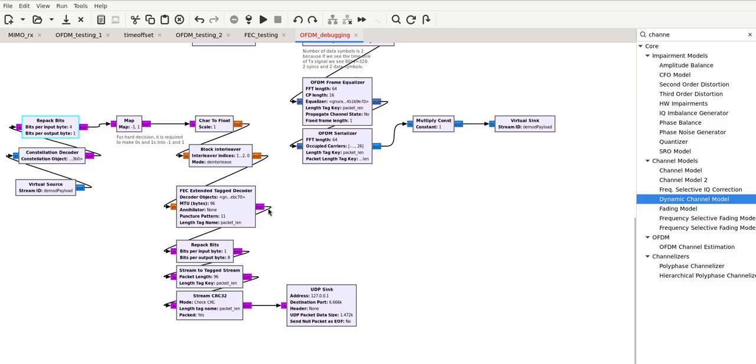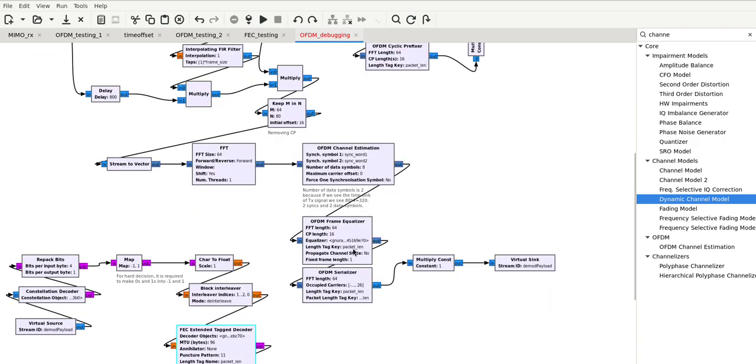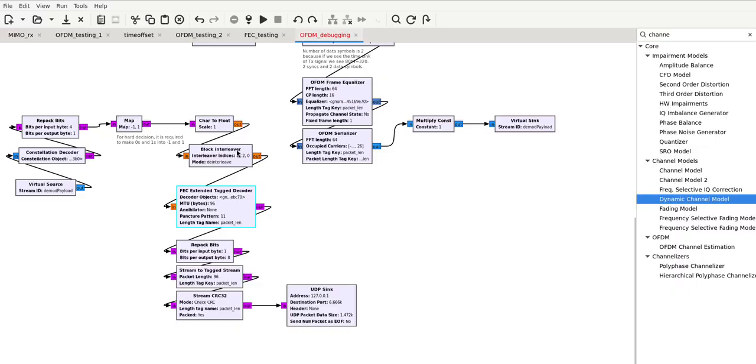Because we are using the FEC decoder, which only takes in soft symbols at the input as floats, but we do not have any noise in our system, in order to produce soft symbols, from the documentation we can see that by simply converting zeros and ones into -1 and 1, we can make our decoder work with hard decision.